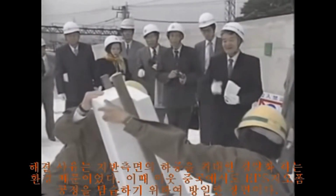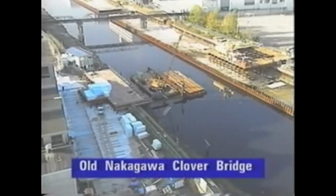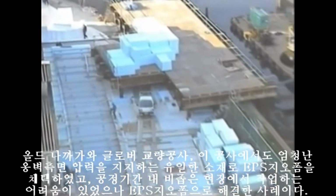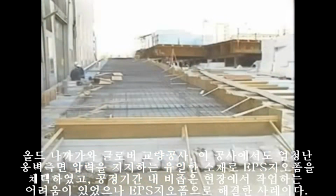In the Nakagawa Clover Bridge retaining wall project, EPS Geofoam was utilized because of its unique ability to absorb lateral pressure. Since no earth pressure could be transmitted to the river dike, construction had to be carried out within limited space on a very tight time schedule.